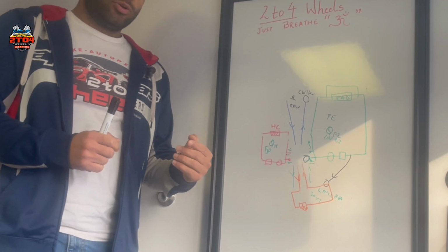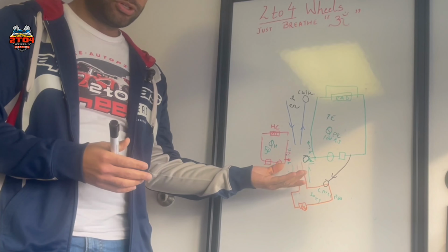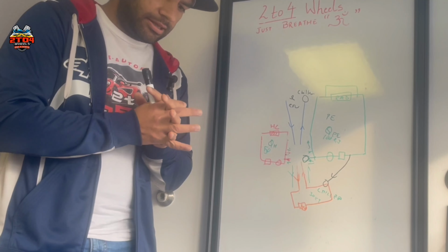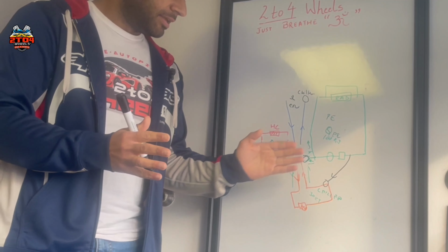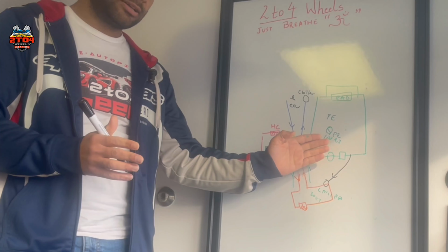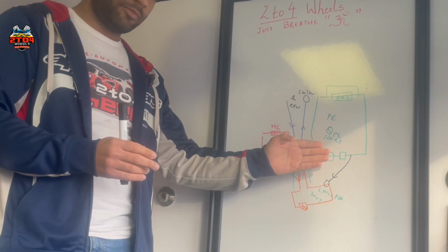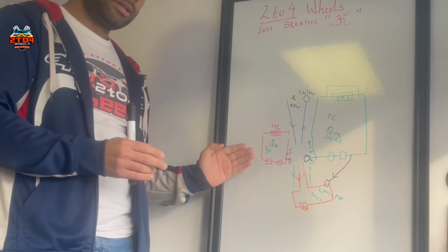So again, Octo Valve being more complex, OEMs have started to use the proportionating valve, but the exact principle is the same. So let's say this needs 50 kilojoules, this has 100 kilojoules. So we just proportionate the flow 50% from this power electronics loop to the cabin loop.